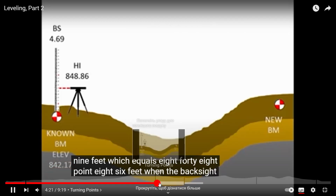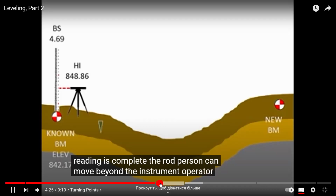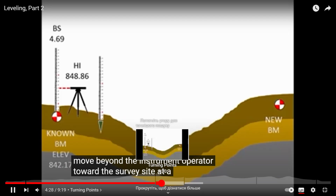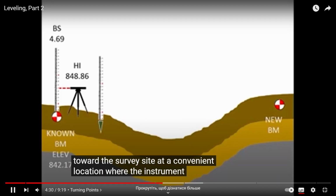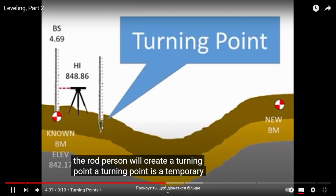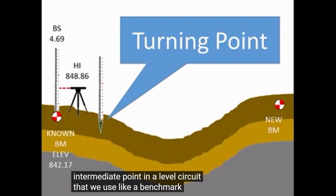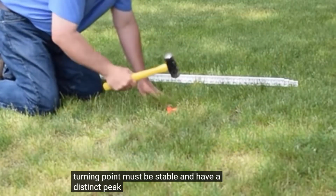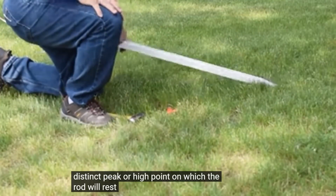And the backside reading of the instrument operator toward the survey site. At a convenient location where the instrument is visible, the rod person will create a turning point. A turning point is a temporary intermediate point in a level circuit. A turning point must be stable and have a distinct peak or high point on which the rod will rest.